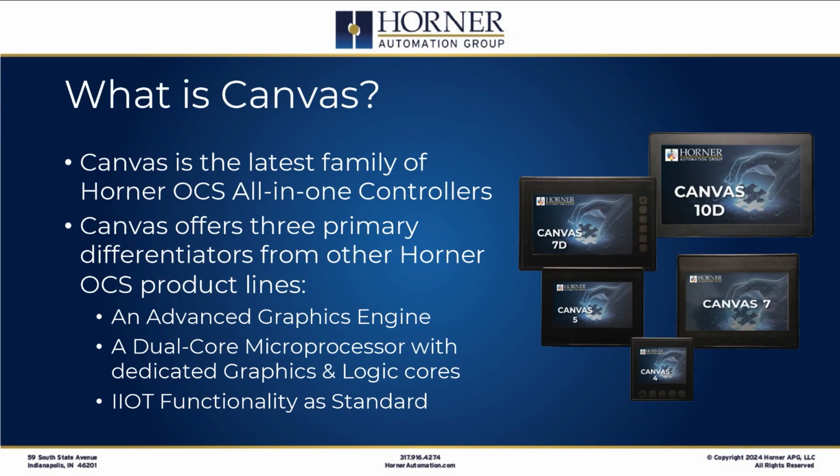Also, the third thing that is a differentiator with Canvas is that there is IIoT functionality built into Canvas. Now, the features that I'm talking about here aren't necessarily brand new, but they are features that were not necessarily standard with our other products. Things like MQTT Sparkplug for pushing data to the cloud or pushing data to a product like Inductive Automation's Ignition. That is something that has been available, but it was an extra, if you will. It's standard with Canvas. Also, WebMI for remote monitoring and control. That's been available for a while, but we've got an enhanced version of WebMI that we call WebMI Plus that is standard with Canvas.